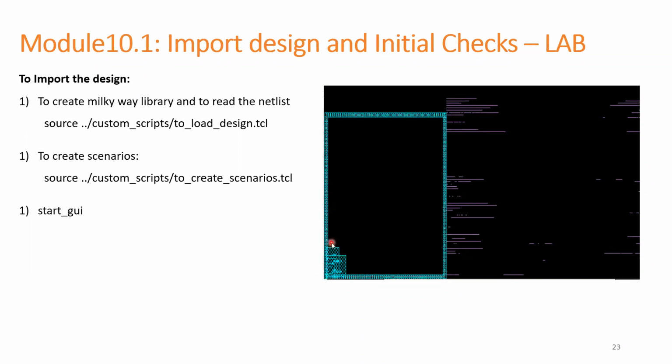When we initialize the design, when we just import the design, the macros will come and sit at the origin only. What we need to do in the coming stage, at the floor plan stage, is analyze the connections between ports and macros, standard cells and macros, and macro to macro. Based on these fly line connections, we need to place the macros across the corners so that there is no congestion. We need to create the proper channel length between the macros. We need to analyze everything at this stage and place the macros across the design.